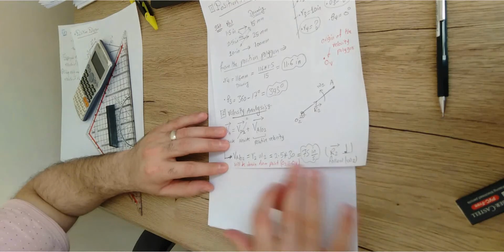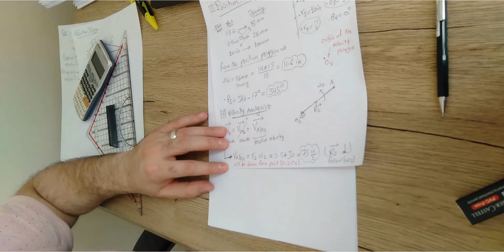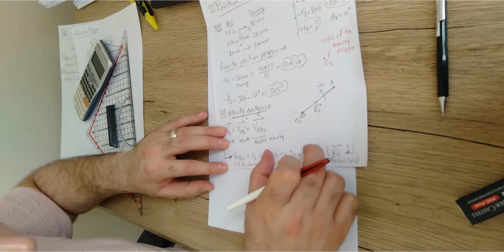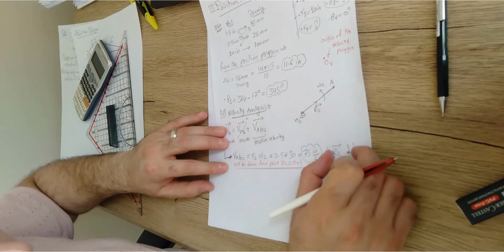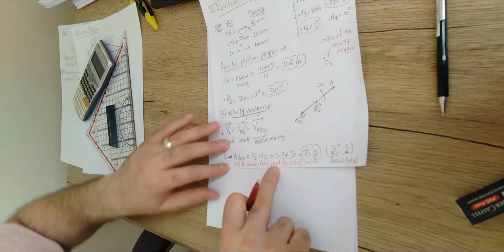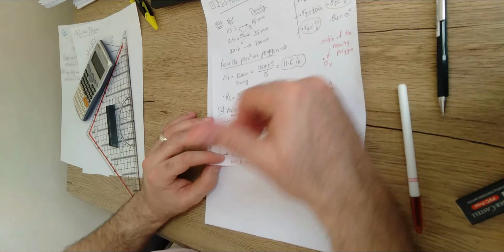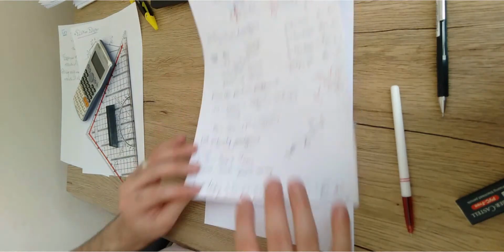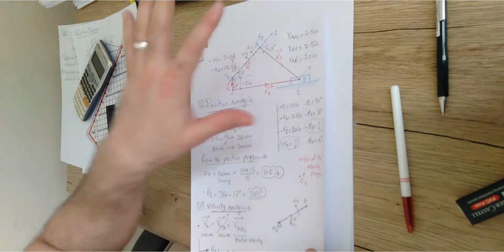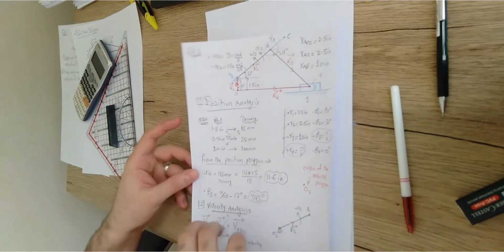Make sense? So here I put a plan. Here I know exactly how I could draw this velocity vector. This velocity vector requires magnitude, requires direction, and requires a start point. From which point are you going to draw this velocity polygon, right? So this is what I did for the first link, which is link 2. I'm going to repeat the same for link 3 and the slider. Here we are drawing for the components of the mechanism. So I'm done with the first link.